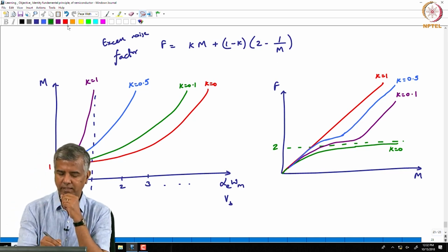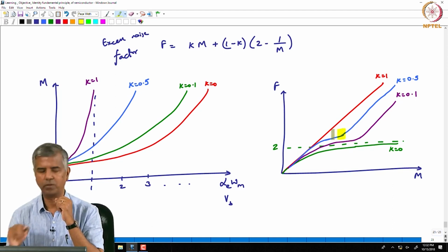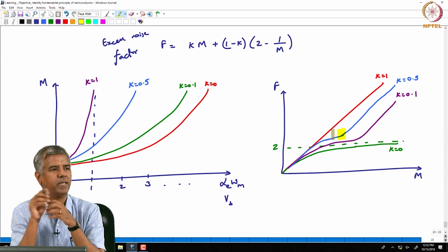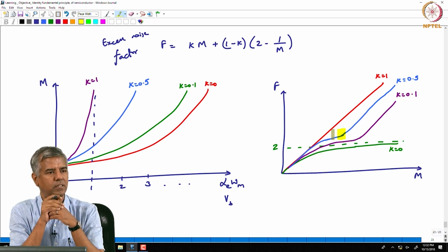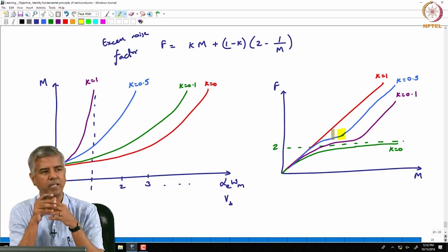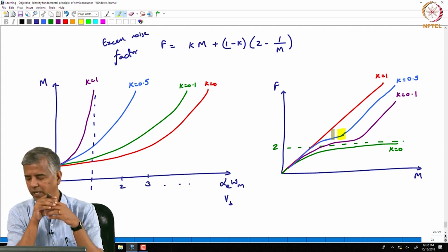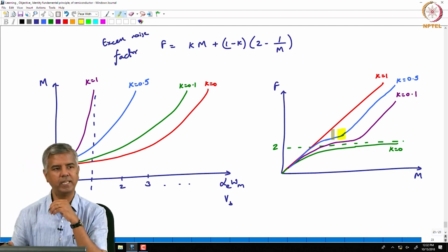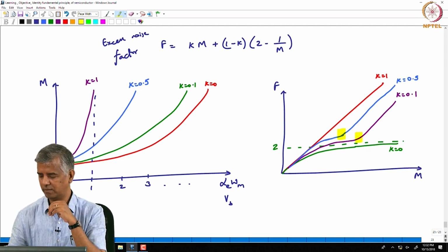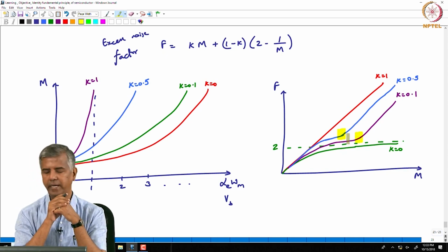right. I would want to operate somewhere over here, the knee point, because until that point I have not accumulated a whole lot of noise, I have fairly good gain, but beyond that point if I am trying to achieve more gain, I am also accumulating noise, right. So, that would be my operating point for indium gallium arsenide, and for silicon somewhere over there, right.